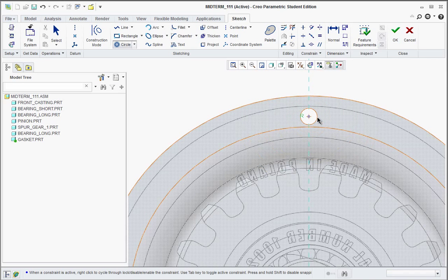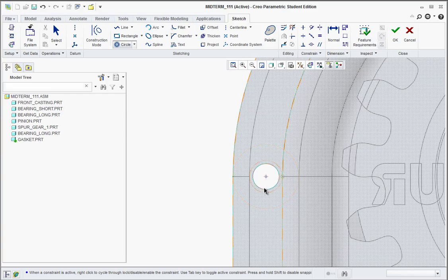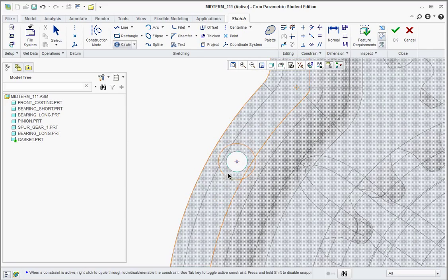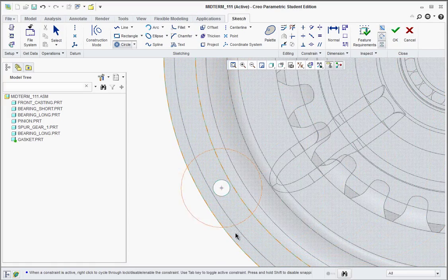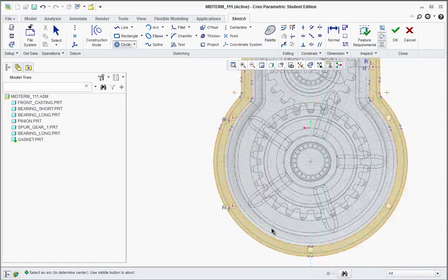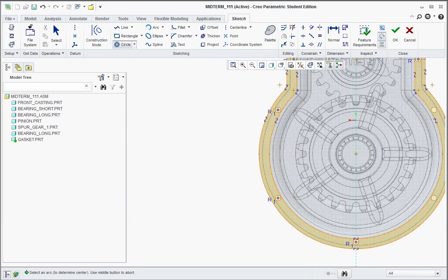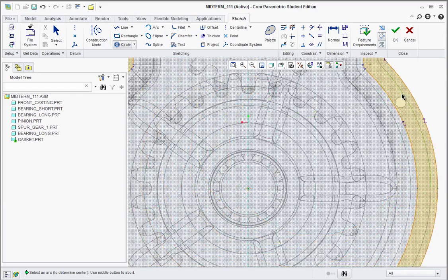Do the same over here. Click on the edge, drag it out, then back in. Click, and when I say click, I'm left clicking. And then once it starts to drag out a second one, middle click to prevent that. Sometimes you might end up clicking twice, and you're going to end up with an invalid sketch. I won't be able to extrude it. So just be careful. You don't want to add duplicate circles on the same edge. Click, click, middle click. Click, click, middle click. One left.